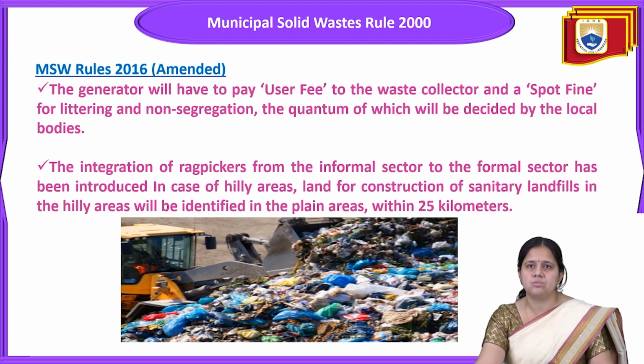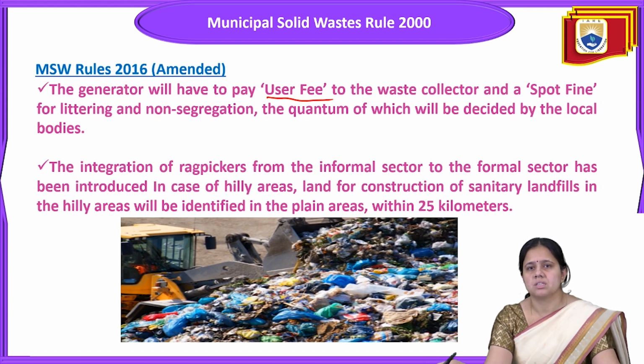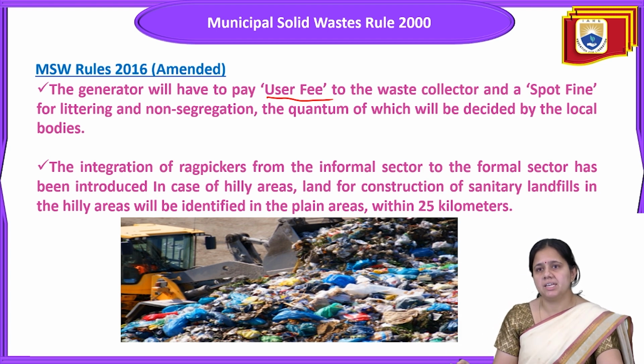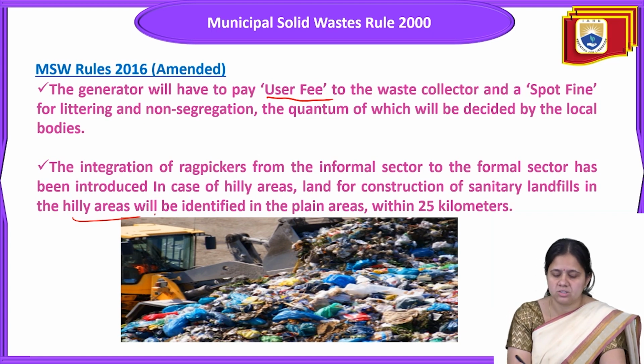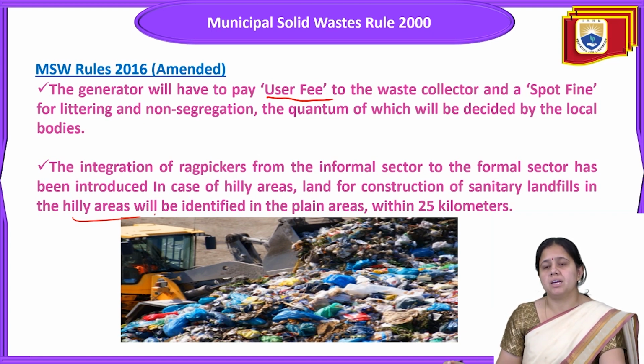The generator will have to pay a user fee to the waste collector, and a spot fine for littering and non-segregation of waste, the quantum of which will be decided by the local bodies. Next is the integration of rag pickers from the informal sector into the formal sector. In case of hilly areas, land for construction of sanitary landfills will be identified in the plain area that is within 25 kilometers. So this is the rule that has been amended.